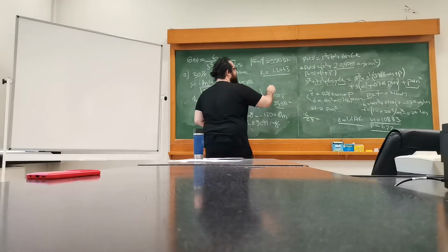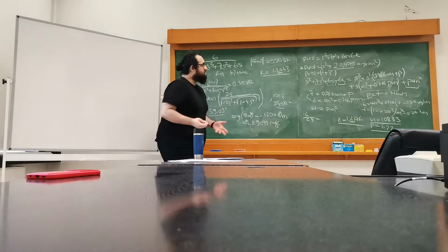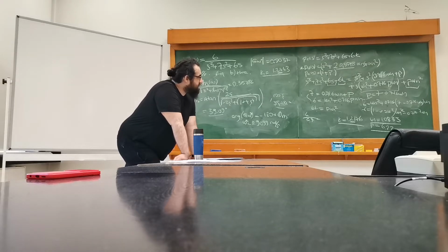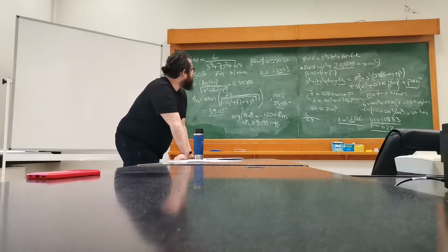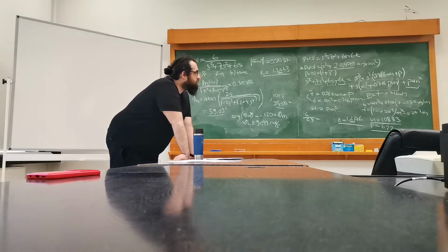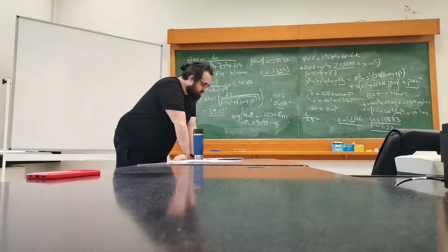By the way, there is a slight difference. You can see that it is 24, whereas we have 21.7, so it's not really that big of a deal for such a system because they're close enough. But yeah, we see that, and this should give us the overshoot value. But the frequency method does not really utilize the system transfer function, but the time domain does. So there's a huge difference in that manner. But we can see that they give basically approximately the same result using the design. So that's basically question 2.